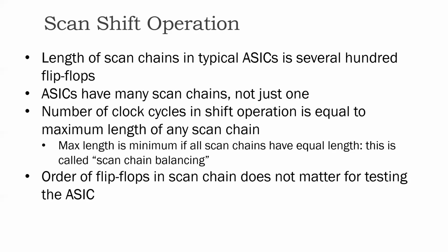The order of flip-flops in the scan chain does not matter for testing the ASIC. The order of flip-flops in the scan chain can be arbitrary. You just need to know what that order is, so that you can populate the right value during the shift operation. But otherwise, what that order is, is of absolutely no importance.